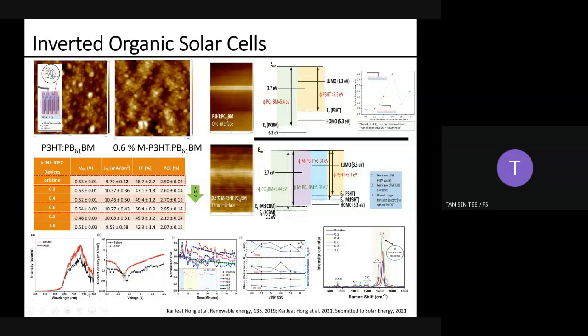Other than that, we also put this sample into outdoor analysis. We encapsulate our sample and then test it outdoors, aiming to study the stability of the devices. We have test conditions under cloudy and sunny weather and also under the controlled system, which is AM1.5G. We found that after we incorporated our system with the metal halide or metal sulfide, the devices show very good stability as compared to those without any modification.